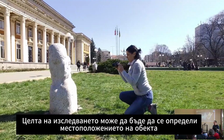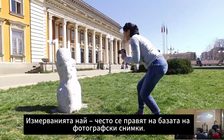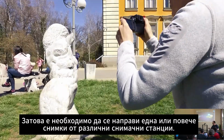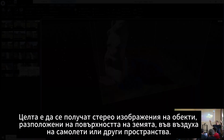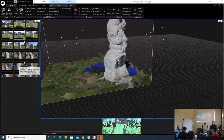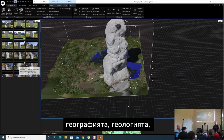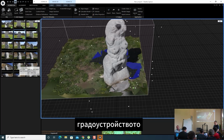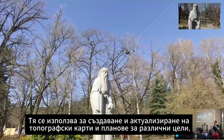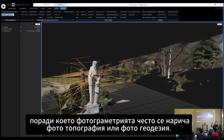The purpose of measurements can be to determine the location of objects in a flat plane, or in three-dimensional space. Measurements are most often made on the basis of photographic pictures, one or more, taken from different shooting stations, stereo images, located on the Earth's surface, ground, in the air, on airplanes, or in outer space. Photogrammetry is used in architecture, archaeology, astronomy, geography, geology, urban planning, shipbuilding, but mostly in geodesy and cartography, to create and update topographic maps and plans for various purposes. That is why photogrammetry is often called phototopography or photogeodesy.